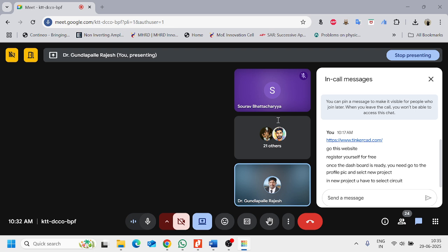See here, digital is in small letters, and for Write, the W is capital, and then RITE, so digitalWrite. Then LED, the variable we have used, and then we have used HIGH. This HIGH is the activation we are doing for the component which is connected to your seventh pin. Then digitalWrite again, and in the same fashion, for the same LED we'll put the status as LOW.